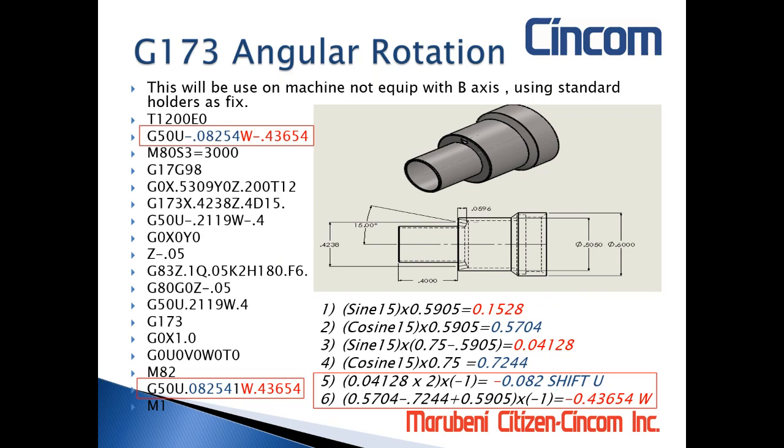So we would like that point to be 0 as if we were on the face of the part. And so the second G50 is changing what the point is now, so that we can call it 0, 0 for this feature. And then at the end of it, we have to change it back. So it's a preference, not mandatory. It's how you like the program.